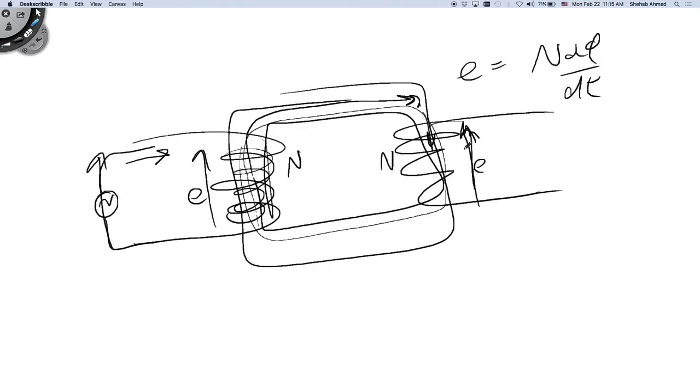The analogy for flux that's flowing in a system and required to generate this transformer action, the analogy for that is an inductor. I represent my transformer in a power system at the end of the day as an inductor. That's the way that I will represent the transformer. I have to find an analogy, right? So what's my transformer doing?